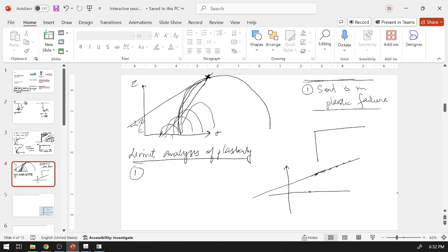So if you have a stress condition like this, you will have the sigma 1 and sigma 3, and you have this as 2 theta. This is the phi. So you learn about active and passive earth pressure. Active earth pressure is when your wall moves away from the backfill such that some of the pressures are released. That is, sigma x decreases.